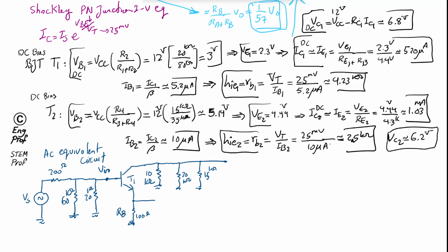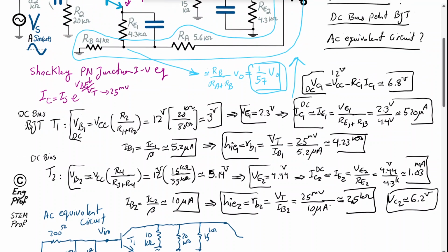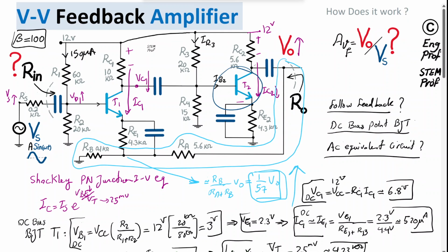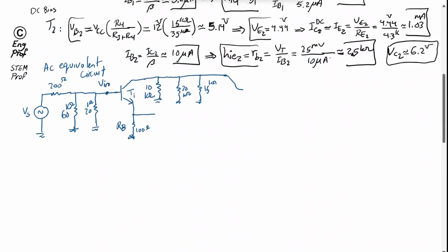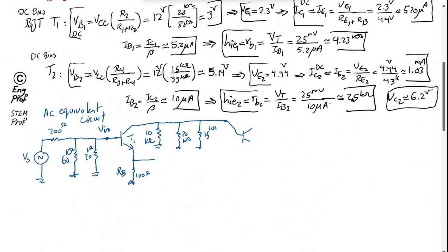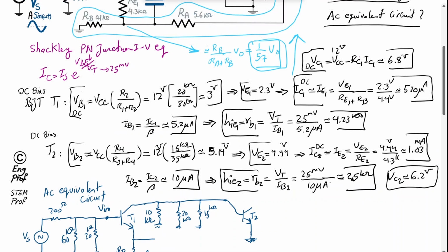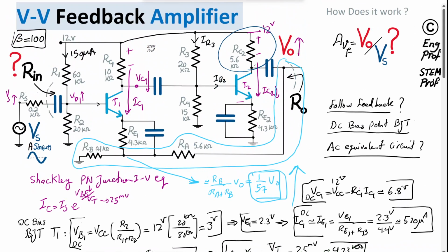And finally, at the base of transistor T2, I'm going to just show it here. So at the base of transistor T2, we get to that, and then the emitter is AC virtual ground because of this bypass cap. So we have transistor T2 with emitter grounded. Okay, and finally we have the RC2 at the collector of transistor T2, and then this is a decoupling cap, shorted effectively AC wise, and then connected to 5.6 that goes to the emitter.